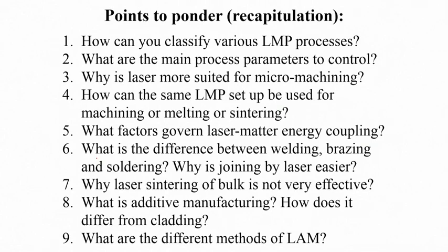We saw that using laser we can do all kinds of joining processes: welding, brazing, soldering. And using laser these joining processes are so easy because I can do it in air, and I can do it for dissimilar things, and I can do such joining even for non-conducting materials, non-electrical conducting, and so on. So I can try and join even an insulator with a metal.